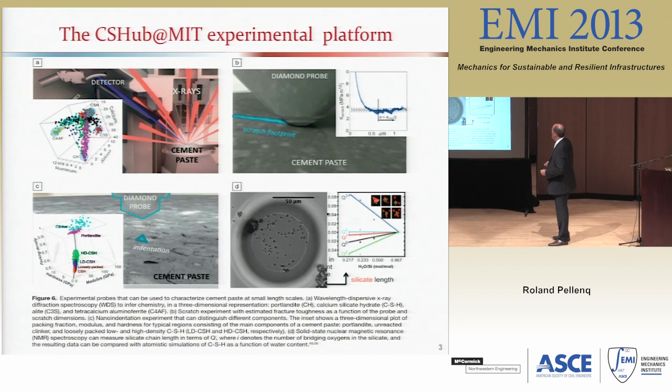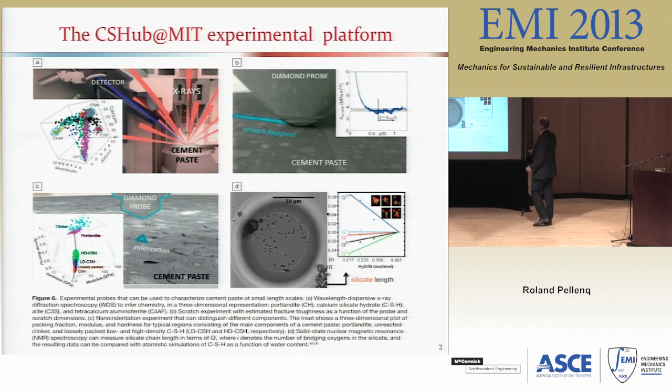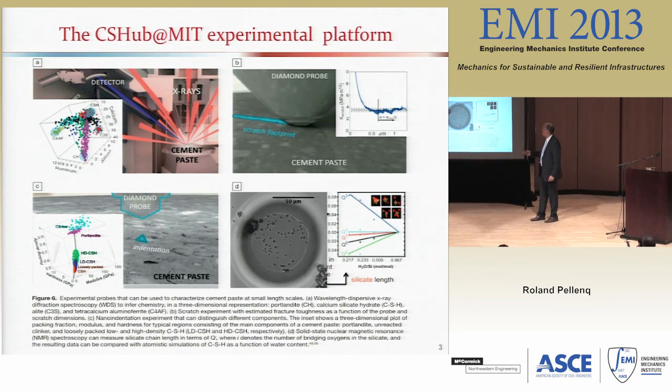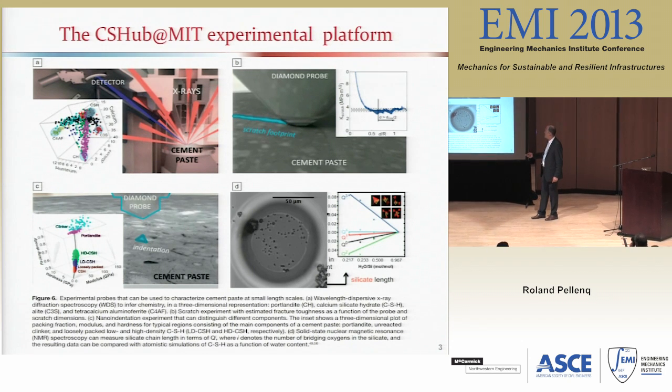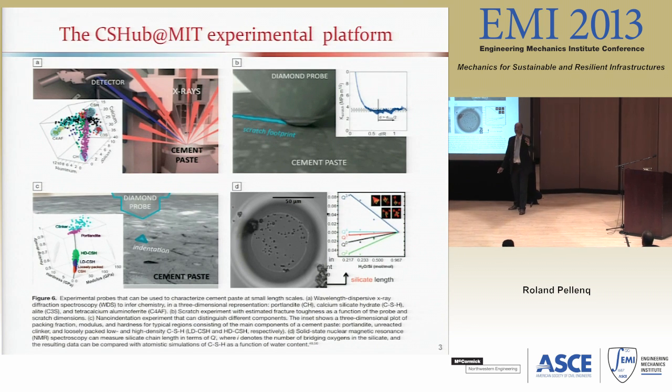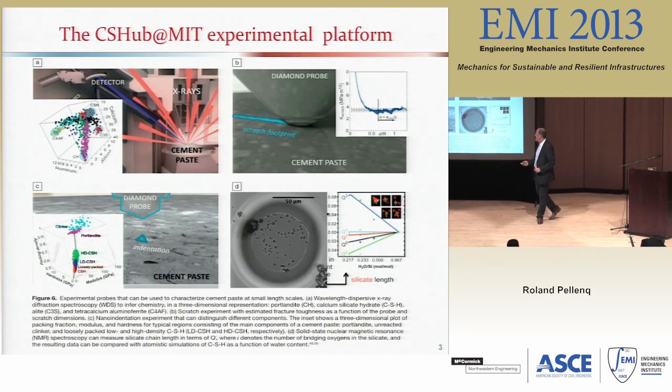In a real cement paste, what we do, this is really Franz Ulm and his team doing experiments, is also nano-indentation. You nano-indent, but not only once, just this little triangle, but you do an array of nano-indenting imprints, and you run a statistical approach pretty much the same way as you do with the WDS measuring the chemistry. Then you can now access the hardness or stiffness of different phases, and this is how Franz Ulm and Jennings, 5 or 6 years ago, were able to say, okay, CSH is made of two phases, low density, high density. And that's really new.